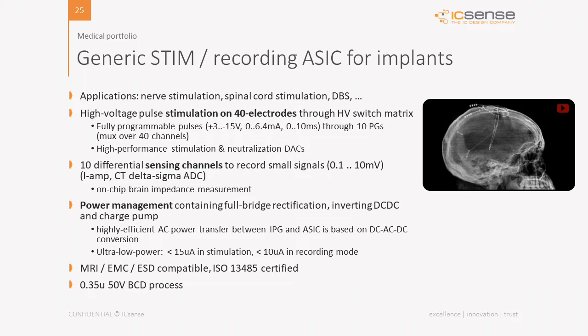Also on this chip, there is some power management that is needed for the full bridge rectification, also the CDC and charge pumps. Also, this case is an implantable device, so we have to take care about MRI, EMC, and ESD compatibility, and also make sure that the chip is ISO13485 certified.